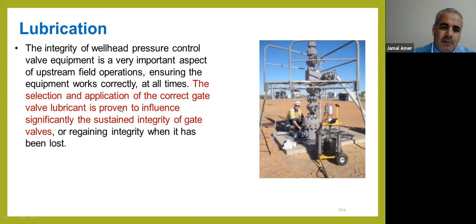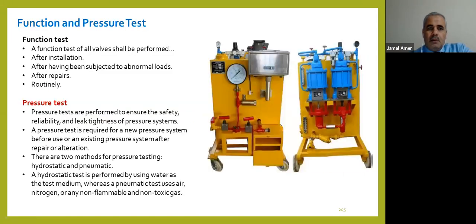The valve could be corroded if we didn't clean it or grease it after an acid job. It will get stuck in the open or closed position. So it makes the situation harder and more difficult and requires more effort to resolve. We have function tests, pressure tests of the Christmas tree and cavity tests. We will do it.